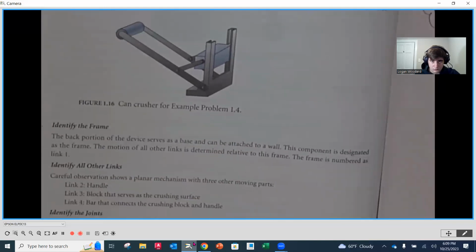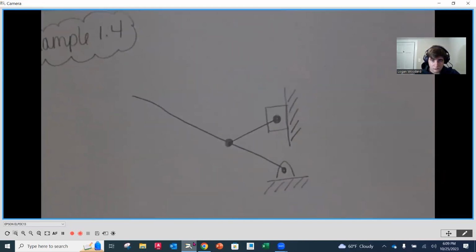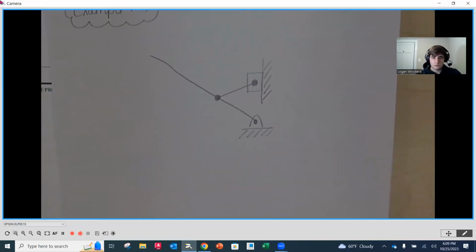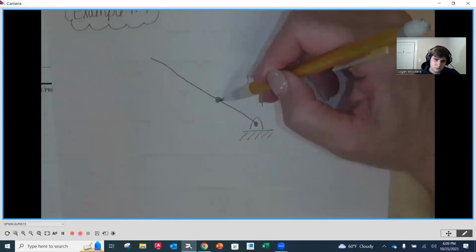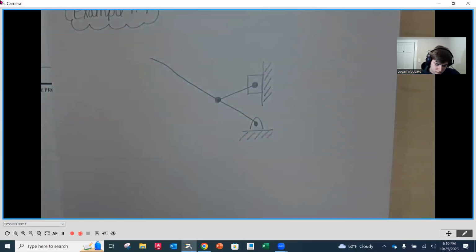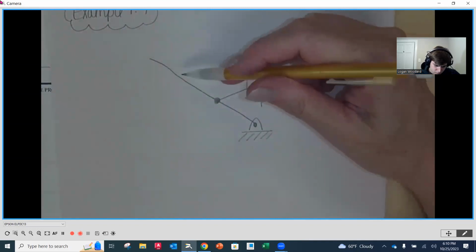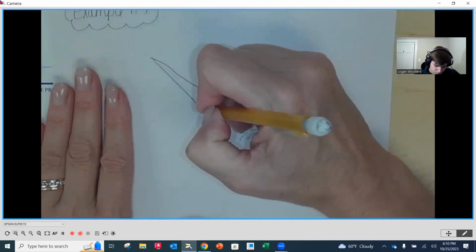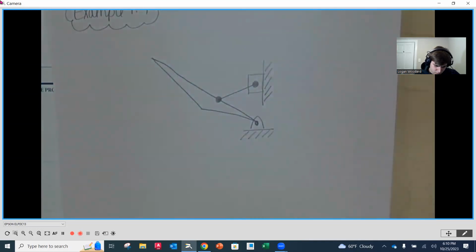All right. I'm going to show mine over here. What do you guys think of mine? Now, I didn't put my labels on yet, but as I'm drawing this, do you notice anything about mine that you would improve? I heard it. Who said that? Triangle. Yes, the handle. Notice that if you don't put that triangle or give it thickness to show that it's a single part, this looks like two different members, right? So by adding that little triangle piece here, it makes it now a solid part, okay?